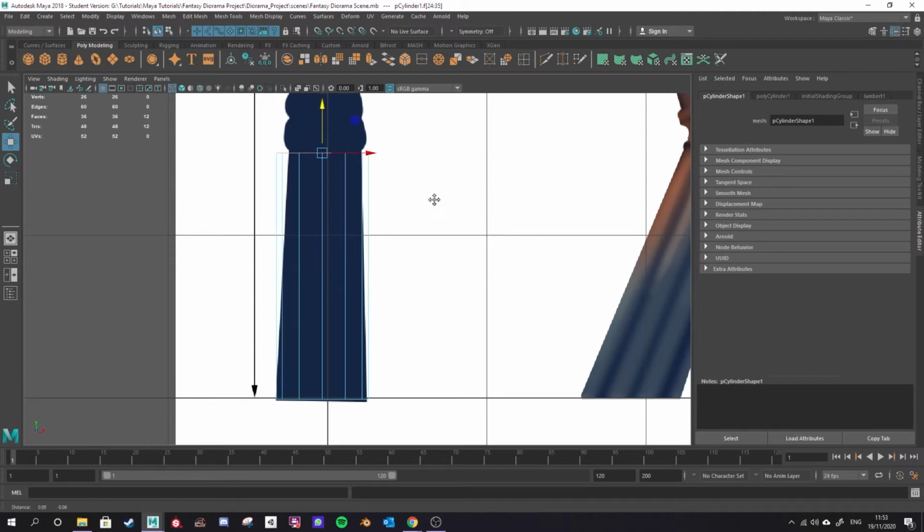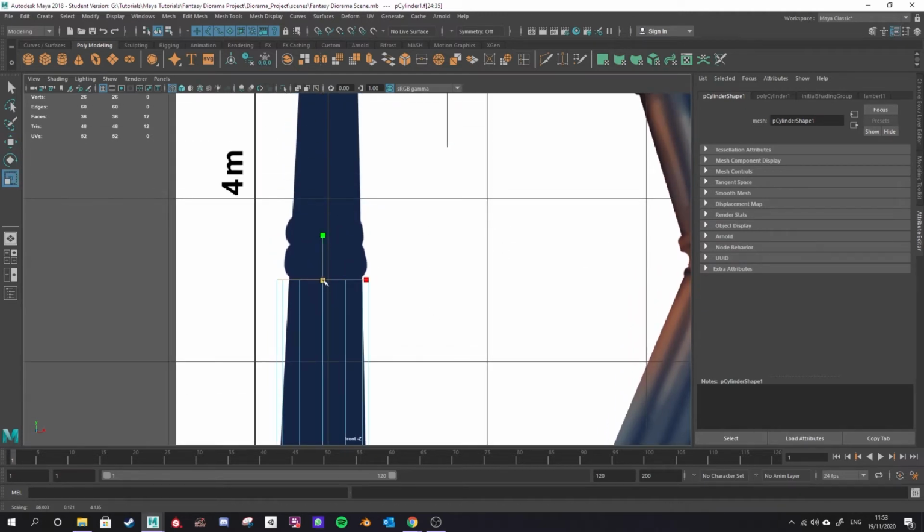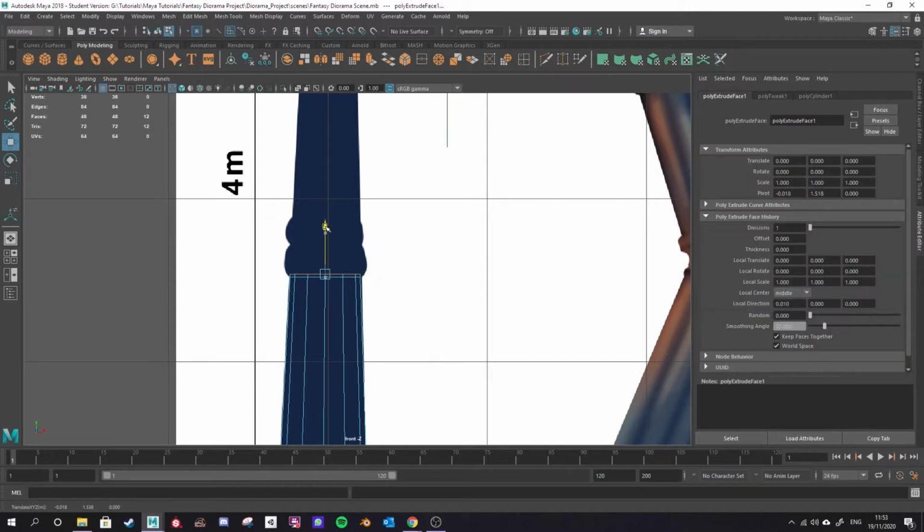One way that I can create the shape is by moving and then scaling my faces that are selected here, then using the Extrude tool, or Control and E, then moving and scaling, then pressing G to use the last tool selected, or again you could use your Extrude tool, again using W to move, R to scale, then G to repeat the extrusion, W to move, R to scale if need be, which I don't here, G to use the last tool, W to move, then R to scale.